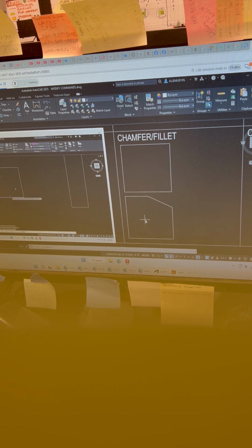So there's the convenience. You don't have to change to a 0 radius if you have the need to keep a particular radius going here. When you need the corner, you just, I'm trying to find somewhere. Here, how about over here? When you need the corner, you just hold down your shift key, and remember, it's not like trim. You want to pick on the parts you want to keep.